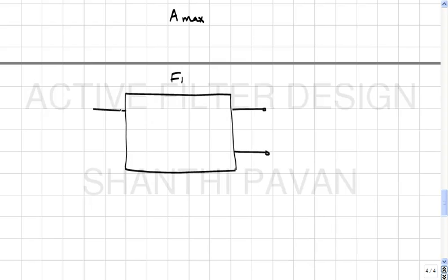For that I need to set the input to 0, and I will measure, because the devices are noisy, between these two nodes. If I place a voltmeter or something, it will keep registering some random voltage, from which I can go and find the noise power.